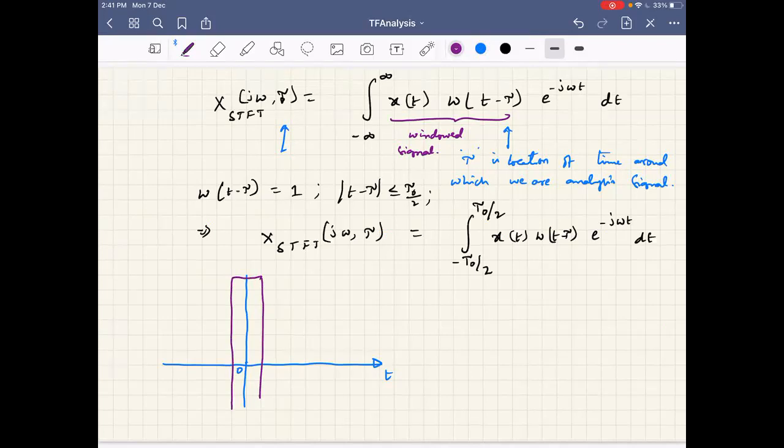So these are the frequencies around t equal to 0. Similarly, you will have some other set of frequencies; this is the frequency axis. The magnitude of the frequencies appears on the z axis, which is not shown here, but is shown as a color bar in plots, or in 3 dimensions as z magnitude in the third axis. Similarly, the next time duration is analyzed, and the next, and the next.